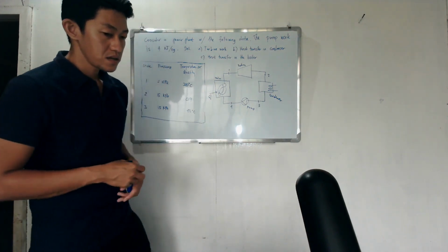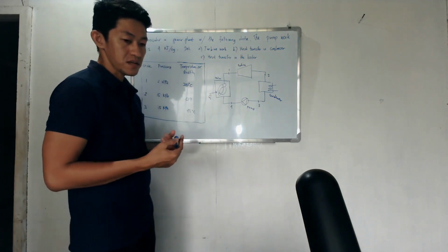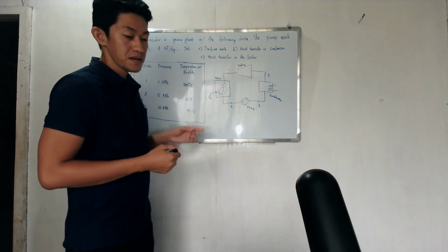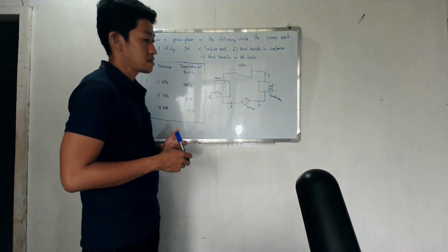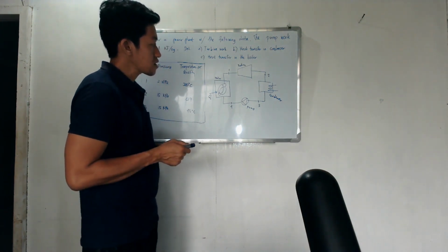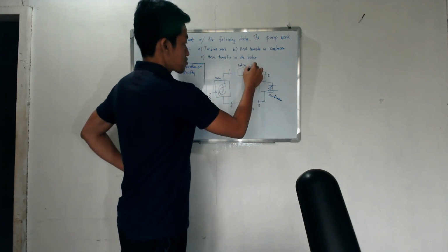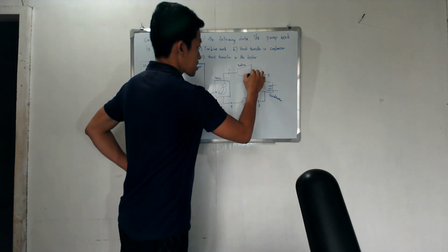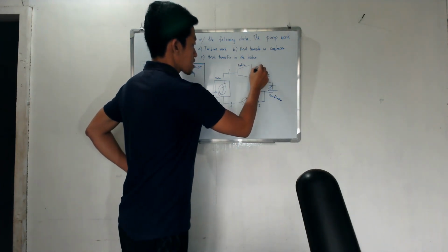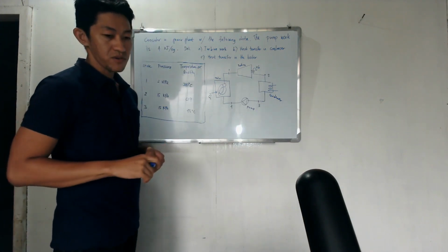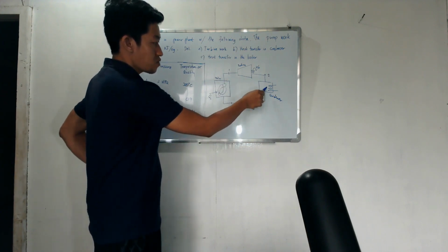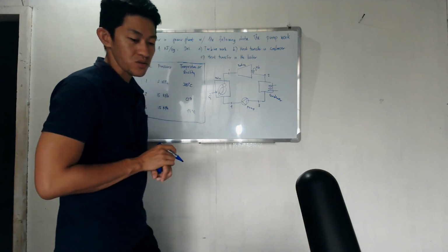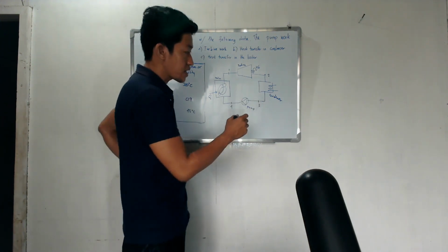In the boiler you heat the water. After heating, it turns into steam. Now the steam is passed through a turbine to harness the energy contained in the steam. In the turbine you produce power, work. Before you return the water to the boiler, you pass it through the condenser to remove the excess heat and to make sure that what goes into your pump is already liquid.